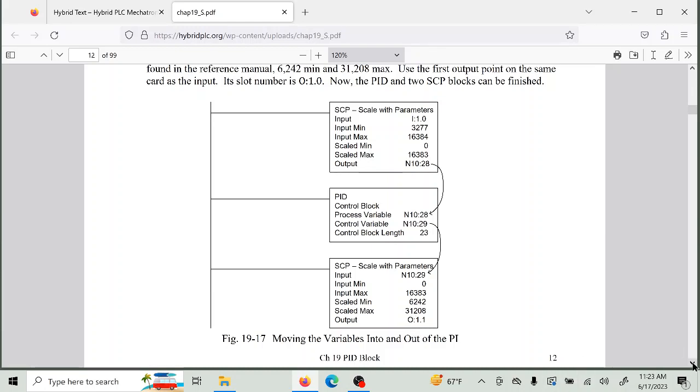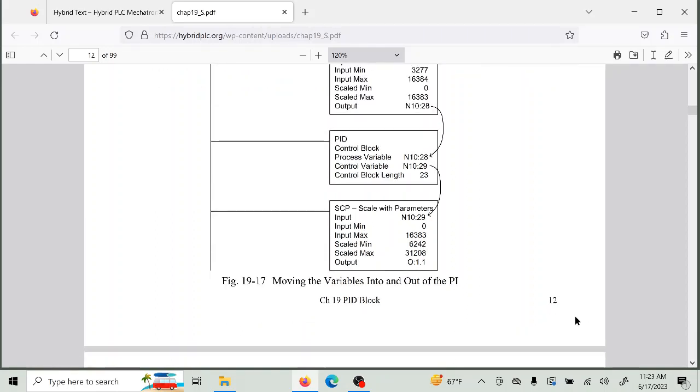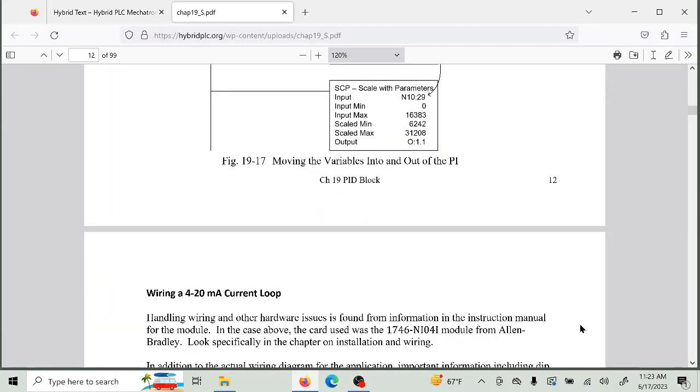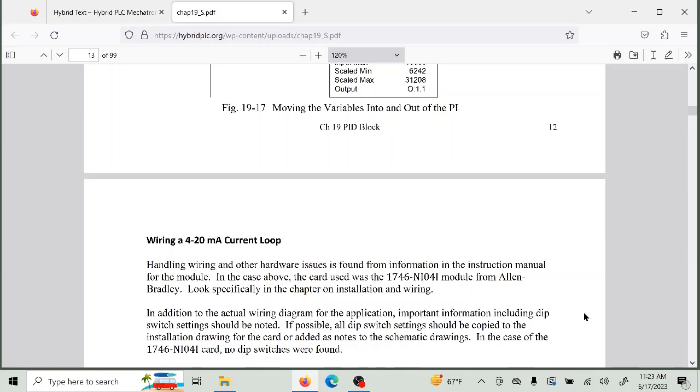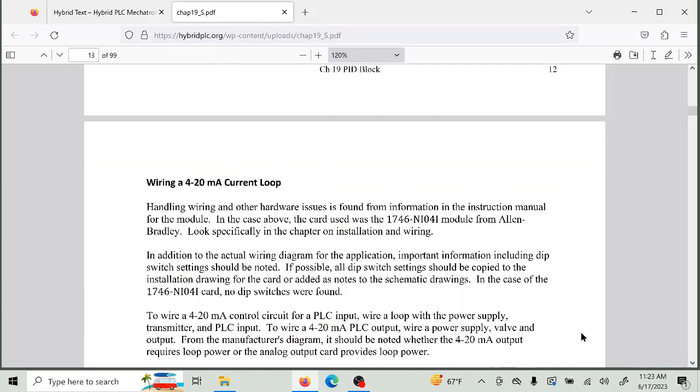And with the Siemens especially, we don't worry about that because all of the data is immediate. But when you have cards stacked up, and in all systems you're going to have those cards stacked up, you have to worry about that aspect of how fresh is the data, how pertinent is the data, and it has to be because you're going to run this on a clock. You're going to run it every 100 milliseconds, every 10 milliseconds, every second, something like that. But you're going to run it on a clock, and you want fresh data. The old rule of thumb is you want it within at least 10% of when you're running it, because if it's 100 milliseconds, you want it in the last 10 milliseconds. You want it fresh. You want it up to date, or else your algorithm isn't going to be very accurate.